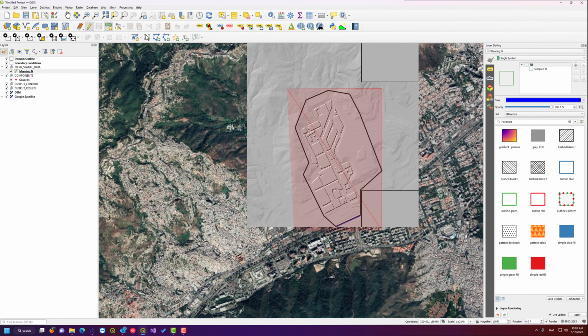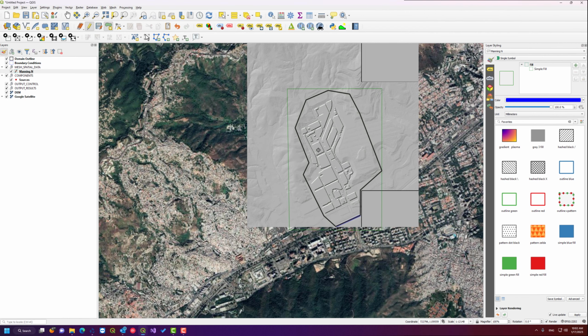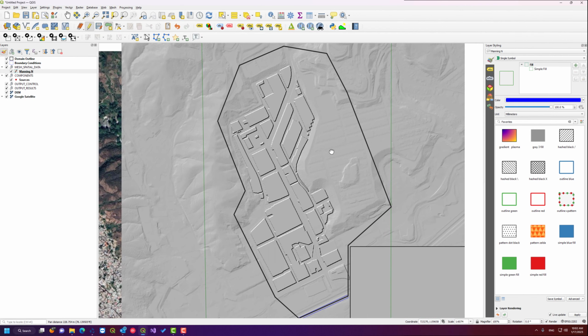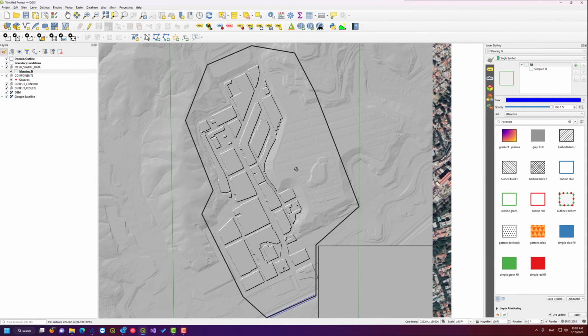It doesn't have to be inside of the DEM. And then I'm going to right click to close. We're going to put 0.003. And now we have a manning n layer. I'm going to save it and turn off edit mode.